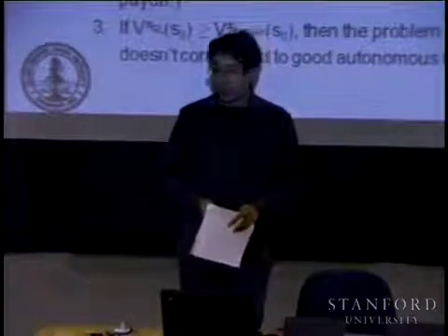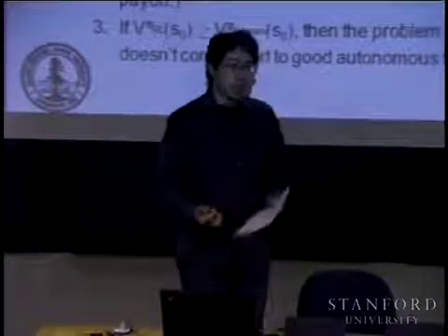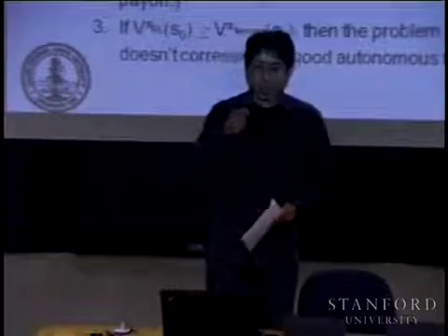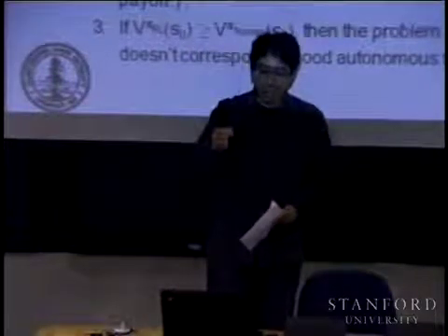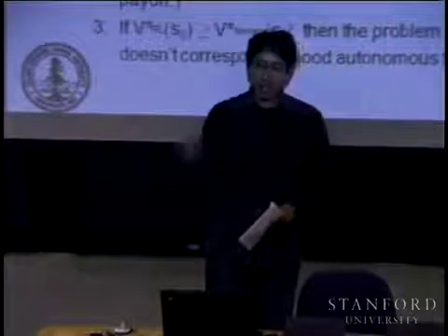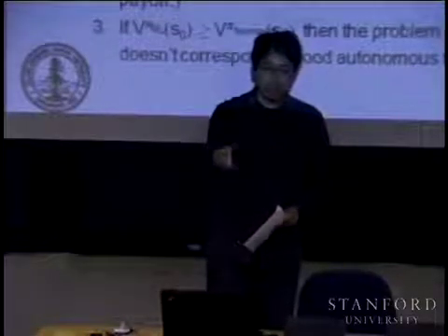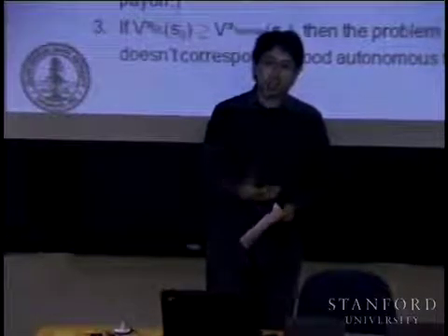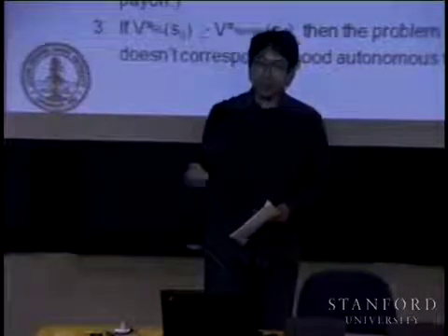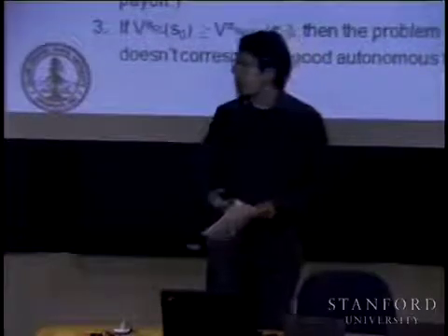And so concretely, what we often do is ask the pilot to carry out frequency sweeps. What that means very informally is imagine that I'm holding a control stick in my hand. Frequency sweeps are a process where you start off making very slow oscillations, and then you start moving the control stick back and forth faster and faster. So you sweep out a range of frequencies, from very slow sinusoidal-like oscillations until you go faster and faster, and you're jerking the control stick back and forth.